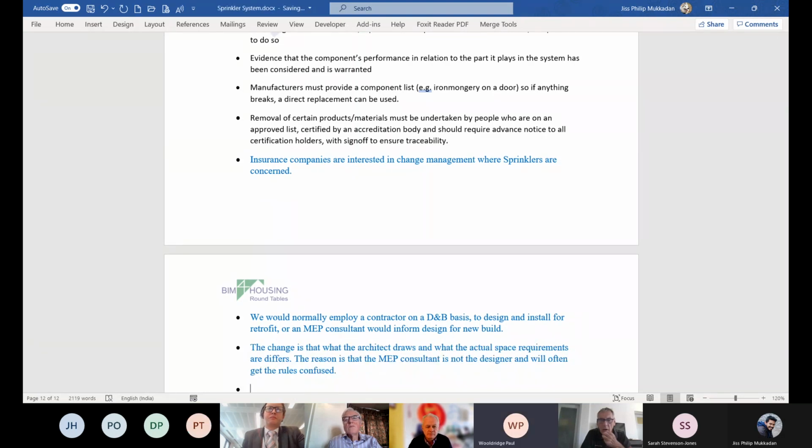Just a point that might be useful to people is that we've looked at the guidance around this, and we're currently rewriting our employer requirements on the development side because there's statutory, as has been mentioned, 11 metres plus. But when you get into funding and guidance around that, for instance, GLA, so London, anything you're doing in London on the social housing side, all buildings, regardless of height, all new buildings have to have sprinklers in that sense.